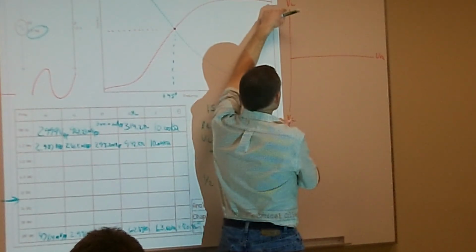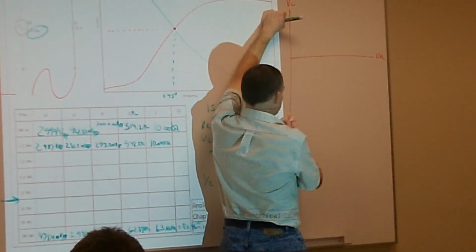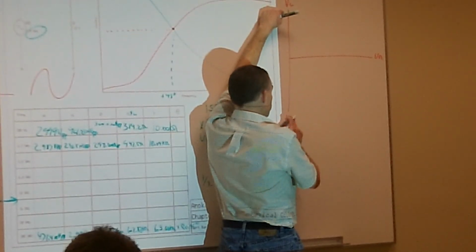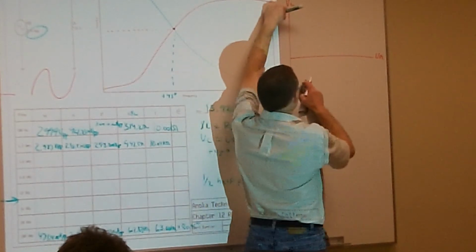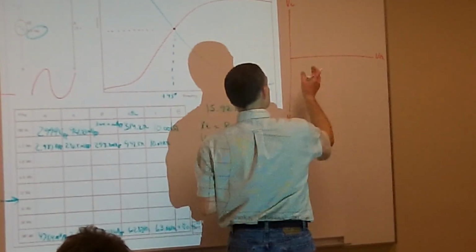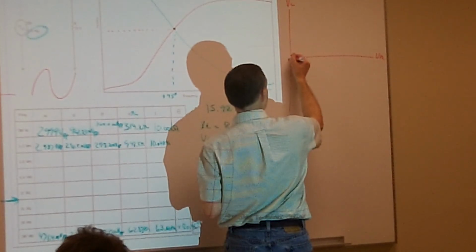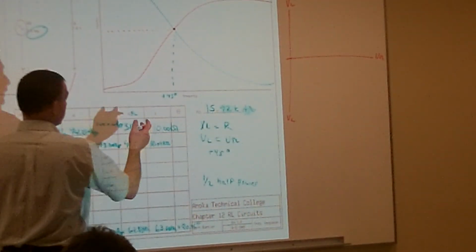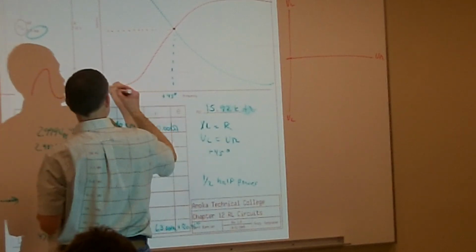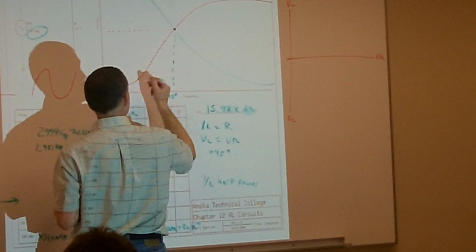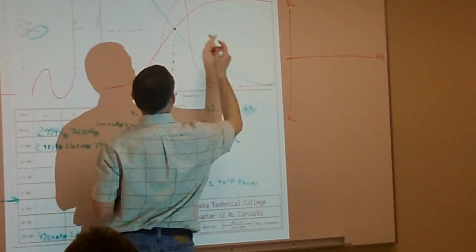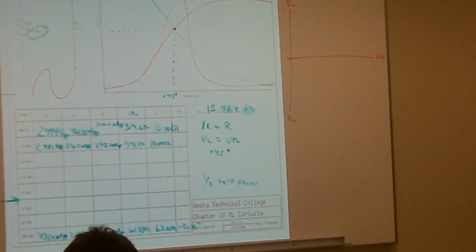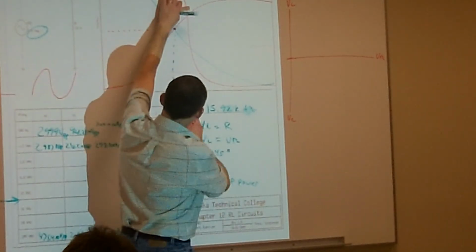And what's going to happen is that this inductor is going to induce a voltage, and this capacitor is going to absorb that energy. And then depending on what the frequency is or where it's at in the phase, the capacitor is going to put the energy back into the circuit, and the inductor is going to have the opposition to that. And so those two are going to end up canceling out. We're going to take a combination of the VL and VC in our circuits there, and what's going to happen is that instead of being either a low pass or a high pass, we're going to get a band pass, and we're going to be able to filter out frequencies on either side of that. And the only thing that's going to be our allowable frequency is right at our frequency cutoff.